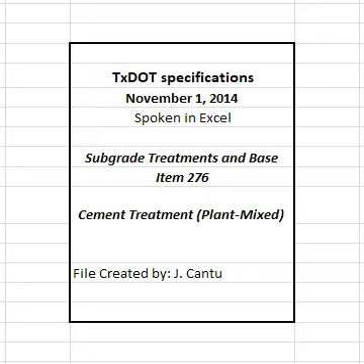Equip plants with automatic proportioning and metering devices that produce a uniform mixture of base material, cement, and water in the specified proportions. 3.3 Spreader equipment. Provide equipment that will spread the cement-treated mixture in a uniform layer in one pass when shown on the plans. Equip spreaders with electronic grade controls when shown on the plans.